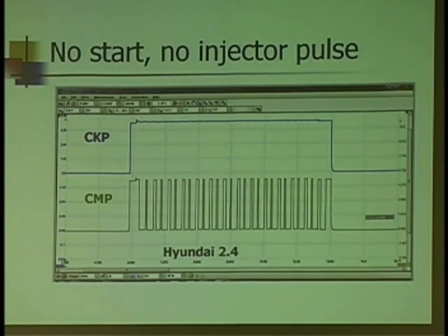Okay. But if you do think of it that way, make sure you understand where you put your leads. When we did the voltage drop webcast, we encouraged you to do your voltage drop test as close to the component as you could get. If you didn't, there was a whole strand of wiring that you were missing, right? Well, that's the same thing here. I've got the leads placed at the harness connector, but it's way at the top of the engine, because if you've done one of these 2.4s, the sensor's not the easiest thing in the world to get to. Okay?